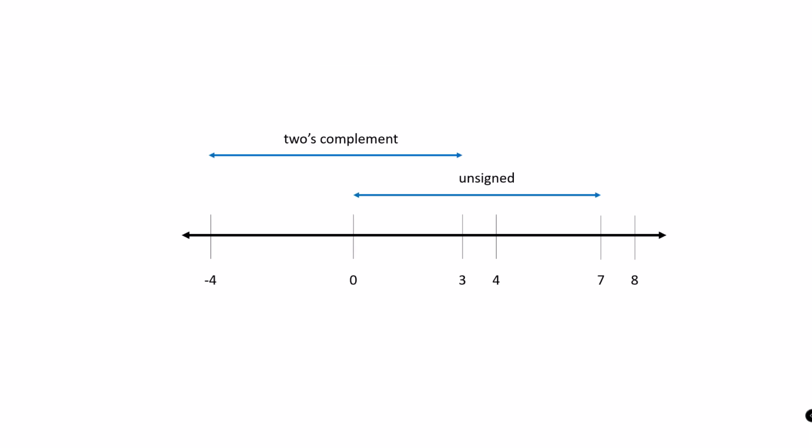Let's spend a minute reviewing computer arithmetic. Programs make use of both unsigned and signed arithmetic. Unsigned can be used for pointer arithmetic, for example. Signed arithmetic is common for applications. Our ALU can use the same logic to perform both signed and unsigned operations. You can see that the unsigned and 2's complement ranges here for a 3-bit value are the same size but cover different parts of the number line. We can interpret the binary number in either way.